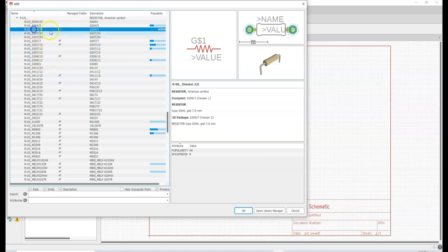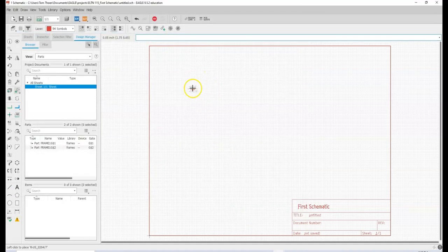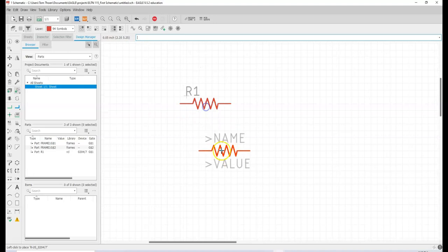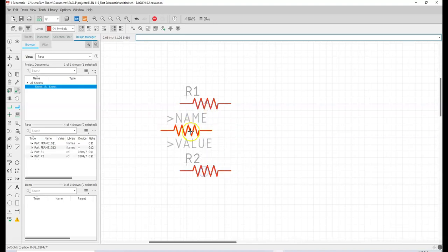But for the most part, we'll use this library component. And if you think, how am I going to figure out where this is? Don't worry, you'll learn how to navigate pretty quickly. And the reference guide I published will have more information on that. Okay, so you'll notice the resistor looks really small. I'm going to zoom in using the scroll wheel here, and I can place it on our schematic. Now you'll notice that it automatically will number the resistors in sequence. Now if I don't want to add any more resistors, I can hit stop.